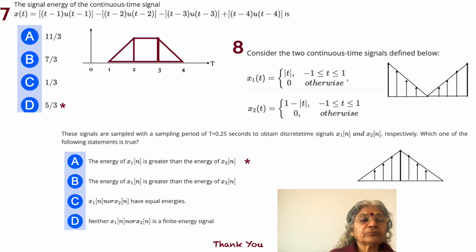Okay, so we have t minus 1 simply read as a ramp with a slope equal to 1. So we start off with the slope, and then we see minus (t minus 2) at u(t minus 2). So we stop at t equal to 2 because the next waveform is going to start off. And what does it say? It says that you are having a negative slope, and the slope is equal, or in other words, the two slopes cancel. So you are having a leveling off of the signal, and it continues in this manner until you reach t equal to 3.